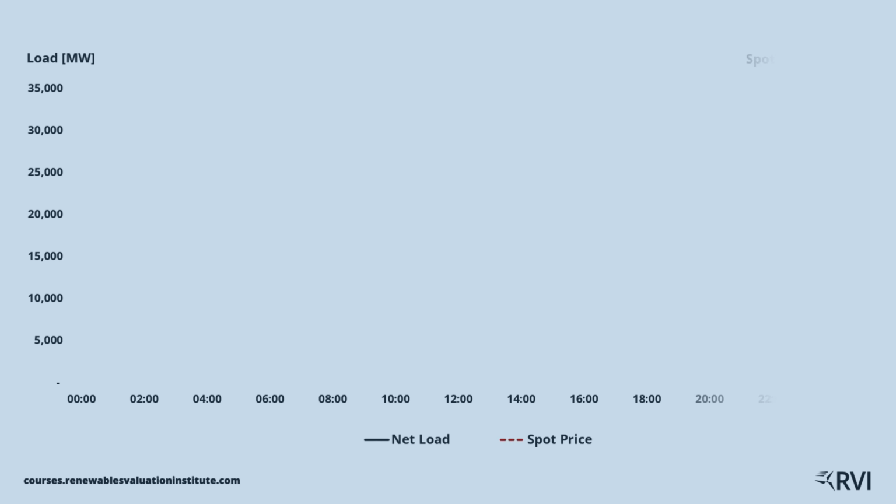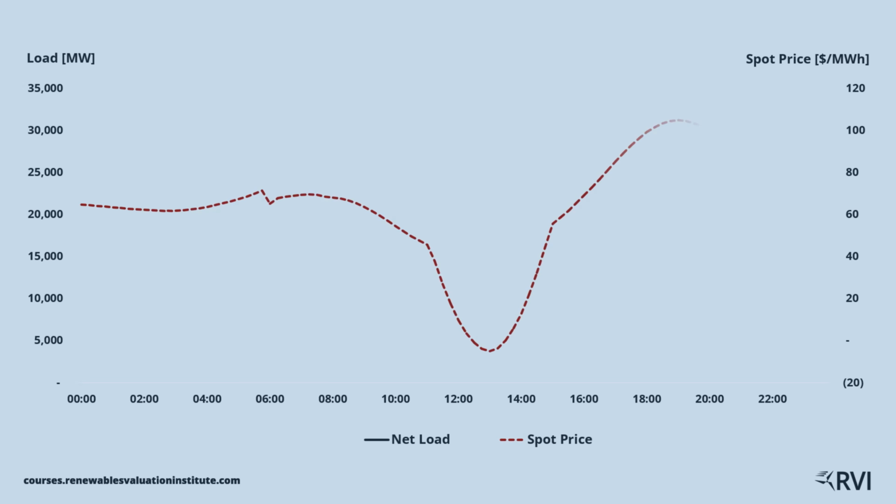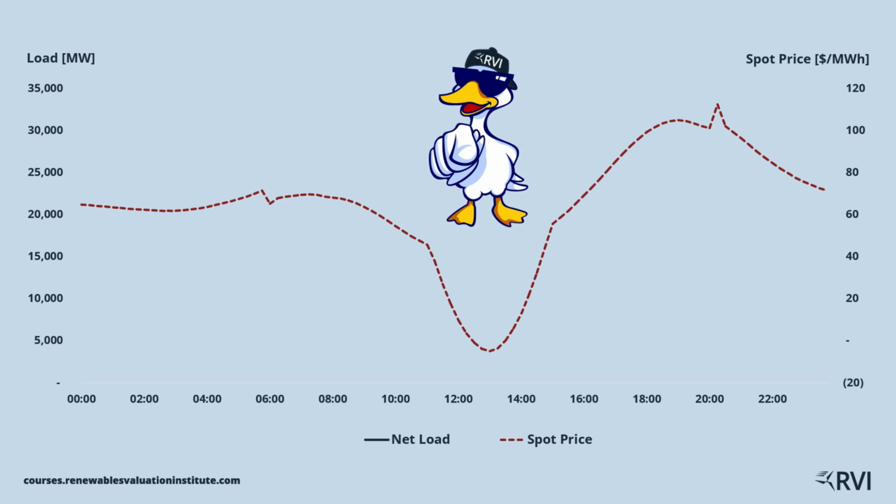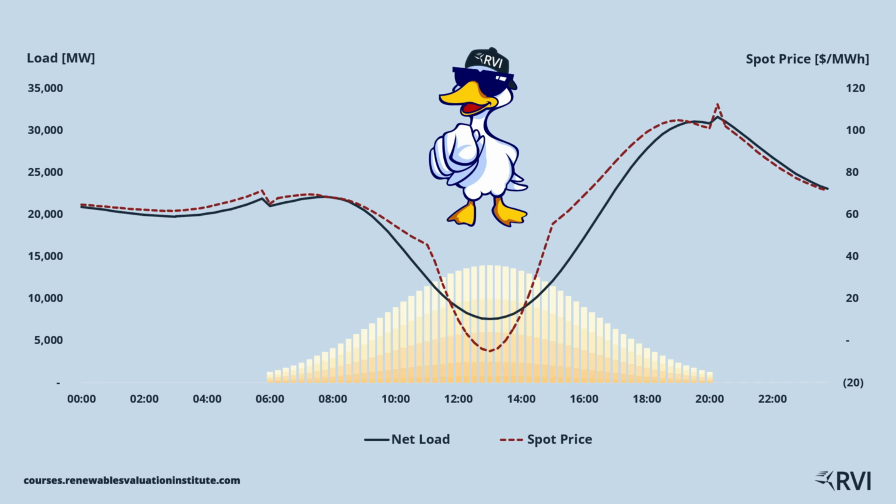Why do prices in solar-heavy power markets crash at lunch and spike at dinner? One idea explains it all: the duck curve. It shows how solar build-outs push net load to record lows at midday, only for it to soar again in the evening when the sun disappears.